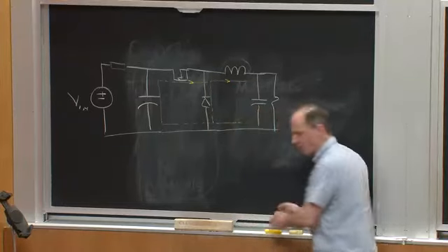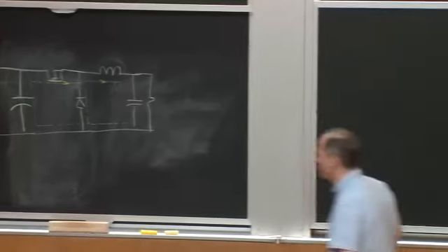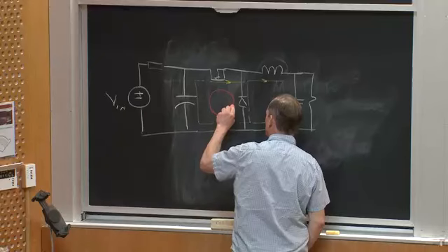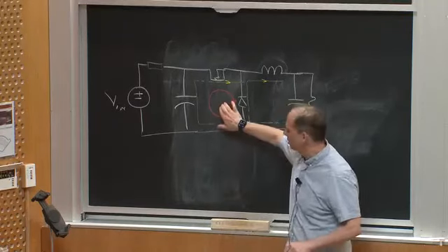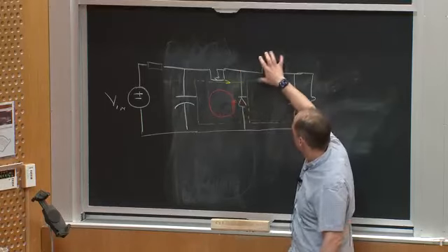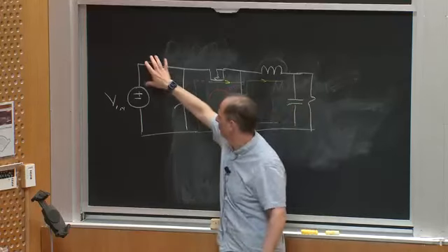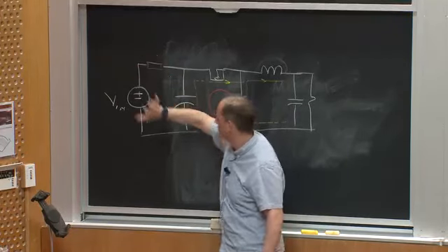So essentially, what dominates the high frequency behavior in terms of high currents is this switching loop here. You can imagine that there's a large AC current running around this switching loop, okay? This branch has almost constant current. If you've done a good job of filtering, this input will have an almost constant current.